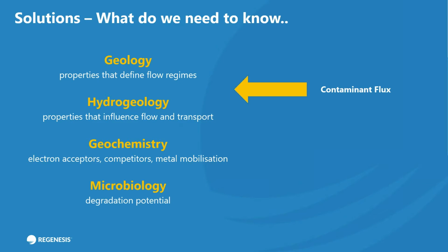It's not always possible, but it's a method that I favor because you're ultimately installing fewer wells, and if you're looking to treat at depth, it's going to be the drilling that's the major cost rather than the reagent and the application. So a series of PRBs can often mitigate against that high drilling cost.